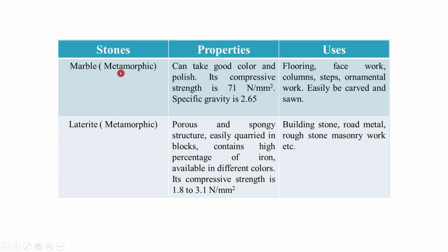It continues. Marble, metamorphic. They can take good color and polish. Its compressive strength is 71 Newton per mm square and the specific gravity is 2.65. They are used for flooring, face work, columns, steps, ornamental work, and they can be easily carved and sawn.